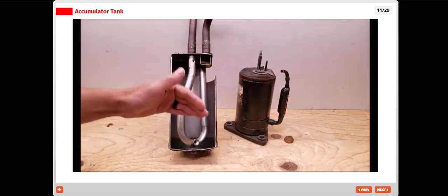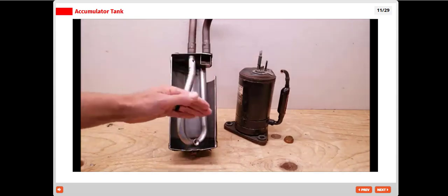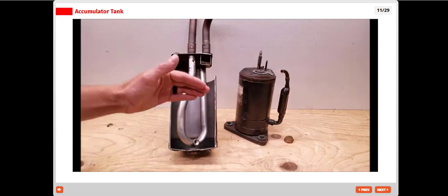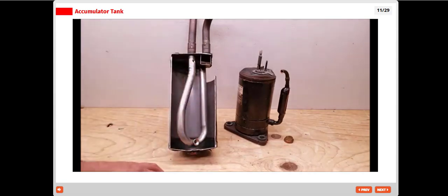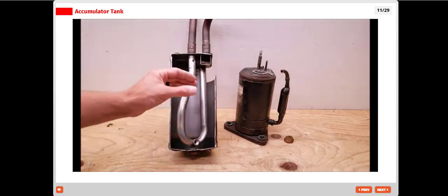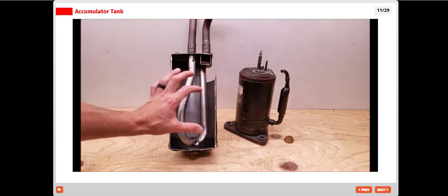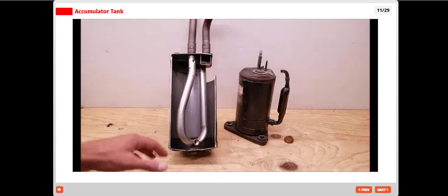And then, say, the mini split would say, after 90 feet, you're going to have to add so much per foot. Or if you're below 35 feet of liquid line set and vapor line set, then you would have to recover some of the refrigerant. But it's going to allow a range of cumulative line set length, so that's nice.